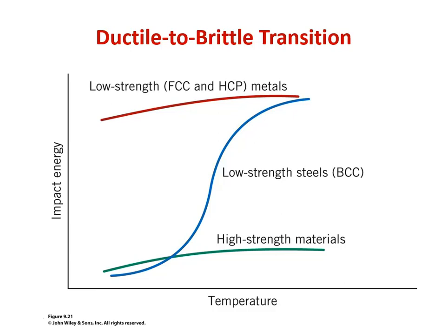And if that range is encountered in service, you can end up with a material that no longer meets your fracture toughness requirements and could fail in service, just like those ships. So that really happened, and it's unfortunately something that happens reasonably frequently.